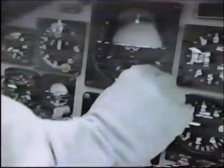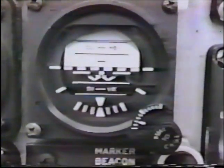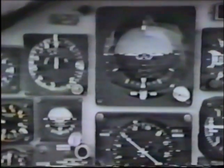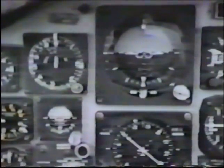Next, align the pitch trim knob index marker on the main and standby attitude indicators with the reference mark on the case. This should position the miniature aircraft on each instrument approximately 3 degrees nose low, which will provide an approximate level flight indication at intermediate cruise altitudes.